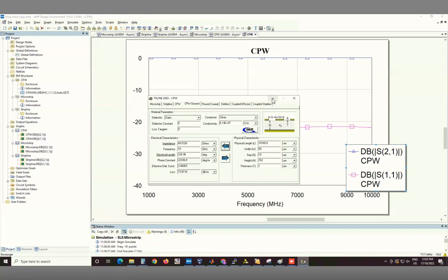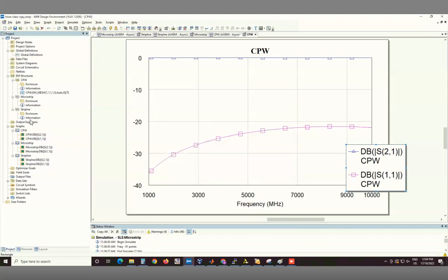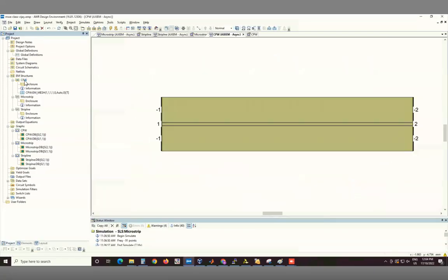The things we connect across in order to stitch the ground planes together, which we have not done so far. And that could be a reason that the impedance is slightly off. But I have no idea as of now, because as I said, the calculation model sometimes varies significantly. But we will try that because I want to show you how to draw those kind of structures in microwave office. And we'll see if actually that makes a difference or not. So in order to do that, I'm going to go back.